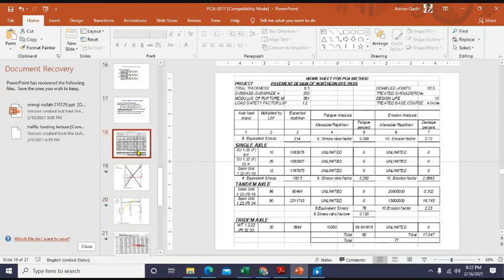For instance, if you have 86, and then we have a stress ratio of 0.282. Stress factor will be used for fatigue analysis, and for erosion analysis you will join 86 with 2 point something to get your allowable repetition for erosion.